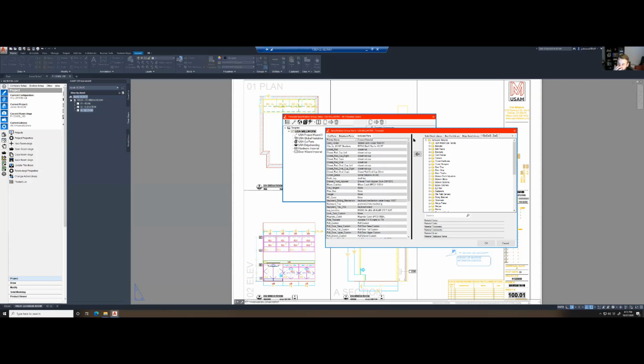Well, and for us, what it does is, if we do optimize through CutRite or Artist, we have both. We can control what board sizes come through there and only make available what we actually have available. So if you want to feed in information from an ERP or from purchasing software and say, I actually only have 10 sheets of 4x8 and 5 sheets of 5x12, you can build yourself prompts that you can actually put that information in.